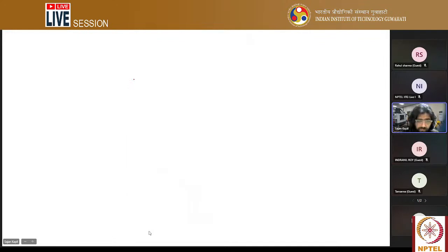So if, for example, this is your build direction, that is plus Z, and there is a triangle at this location, and this triangle has a facet normal like this. I think in this question there is a typo. We were mentioning 45° from here, but this is not what is written in the question. This is what should be mentioned.